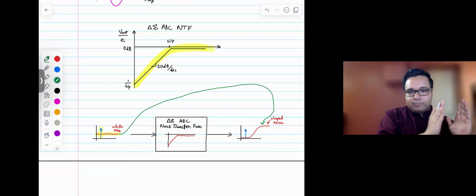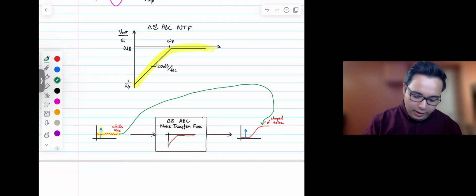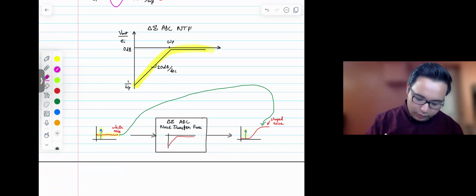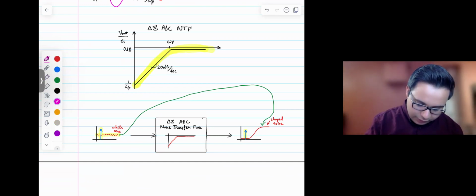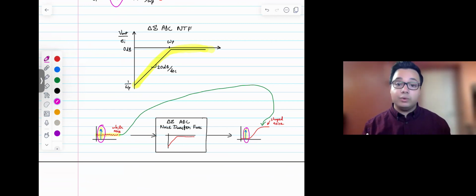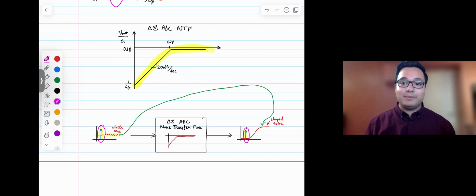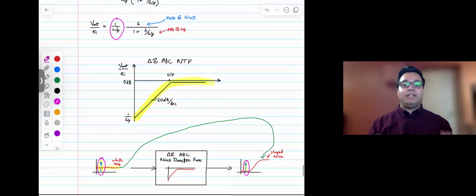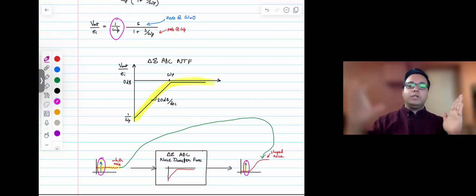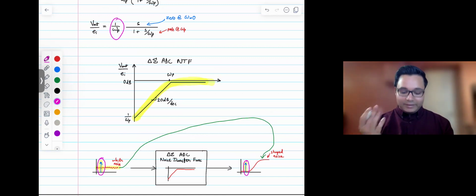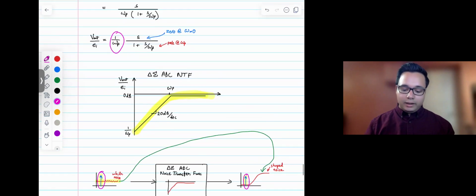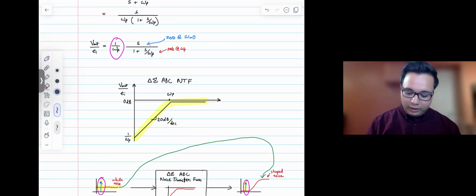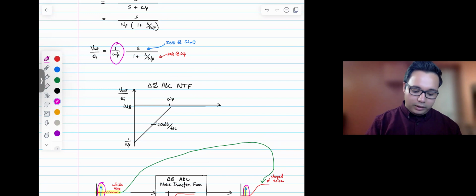So the noise is sort of pushed out of band, and so again, you have your signal just like before over here. But look at the SNR, or signal to noise ratio, over here. Your SNR is better, right? And so that's the idea of delta sigma noise shaping. Basically, you're trying to push the noise out of band, and that helps you get a higher SNR in a delta sigma ADC, and so that's the Bode plot for a noise transfer function for a delta sigma ADC.